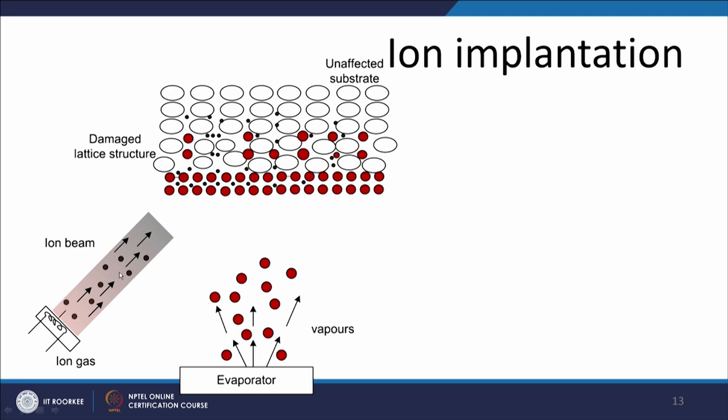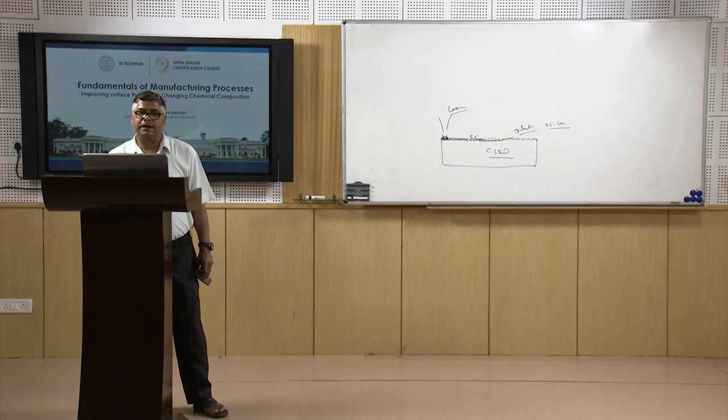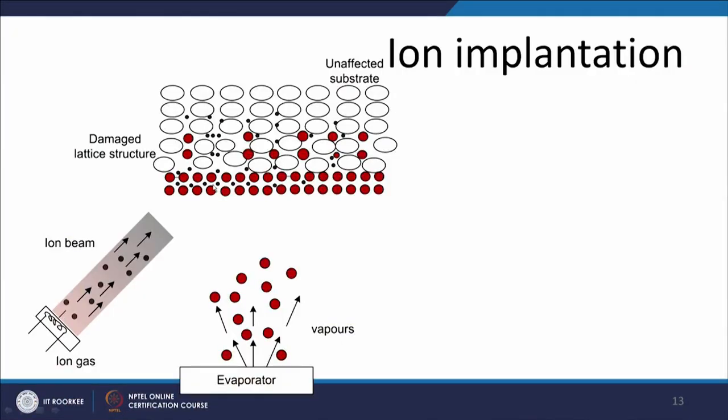When the ion beam is directed at high velocity onto the surface, this leads to increased mixing of these atoms with the substrate material, and thus the surface layers get modified, and the surface layer crystal structure is also modified. Most of the ions and metal vapor atoms are present at the surface, and their concentration keeps reducing with increasing depth from the surface.